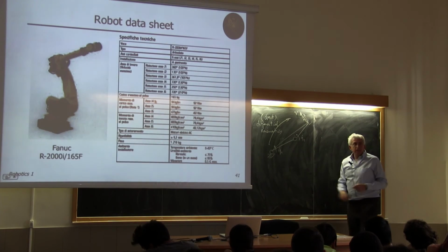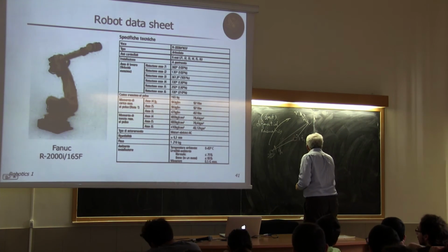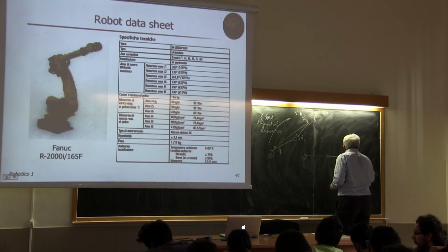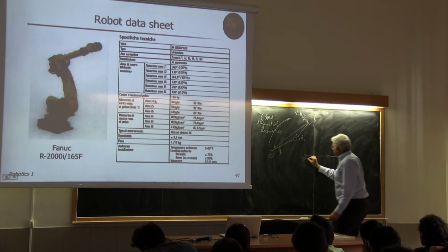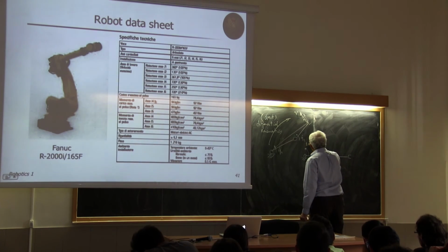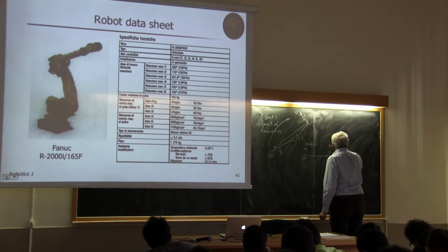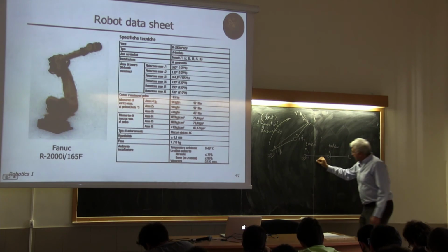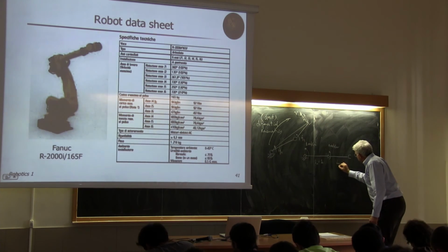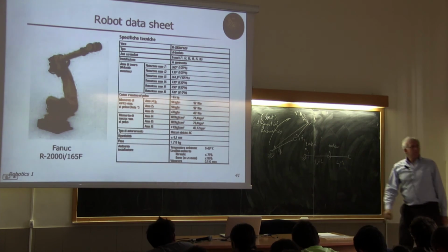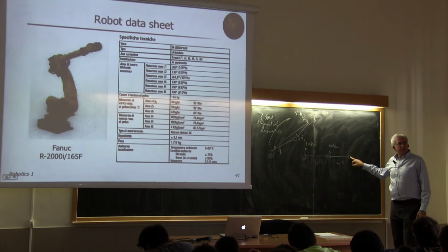Okay, let's take this robot and put some numbers. Let's put it in a very easy configuration. Suppose that this is straightened like this. And suppose that this velocity is 1 radian per second, and this velocity is 1 radian per second, and this link is 1 meter long, and this second link is the same, 1 meter long. Question: what will be the velocity of the end effector?